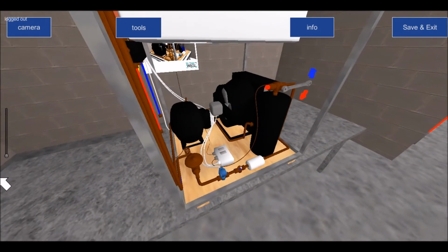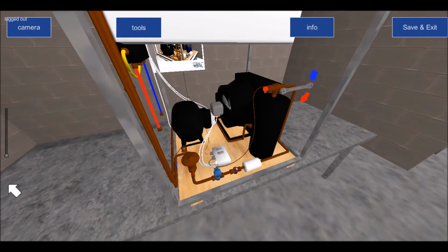Now, using a pump down is actually better because it's less harsh on the compressor when it starts up, because the compressor starts up on a low pressure as opposed to having to start up full of gas. When the compressor is full of gas and it starts up, say it's sitting there at 10 bar pressure, that creates extra pull on the compressor because there's a higher torque to get it to start.